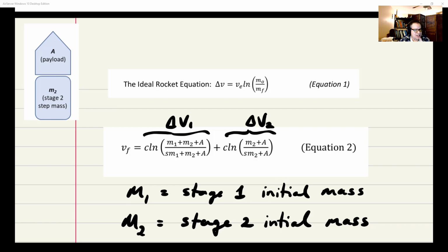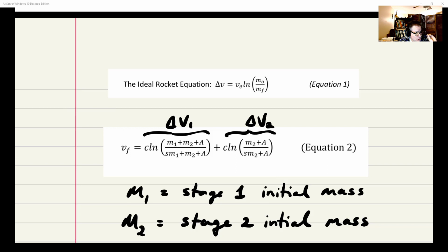Now, an interesting question that can come up here is that when you drop a stage, does that provide any additional velocity? Because you're expelling, aren't you? Aren't you expelling the lower stage? But no, we're not expelling. We're just imagining you just drop the stage. And so that lower stage that's being released would have the same velocity as the upper stage before it begins its burn. So there is no delta V that's gained by just dropping a stage.